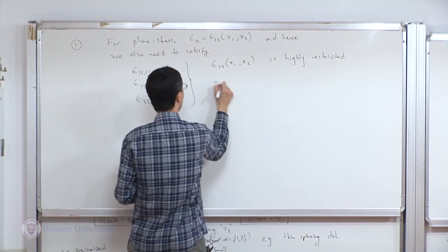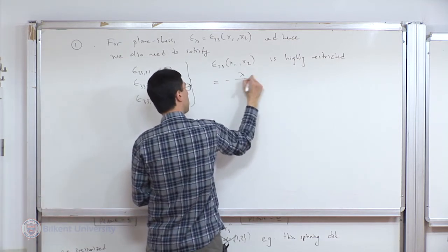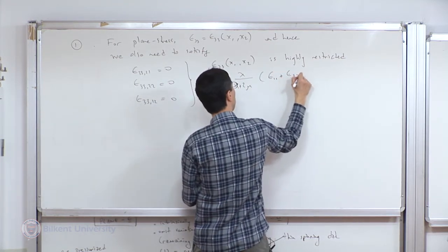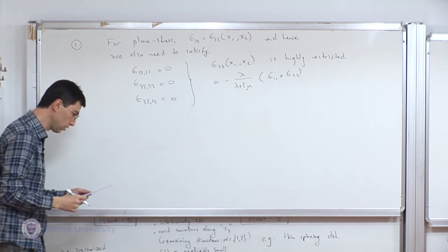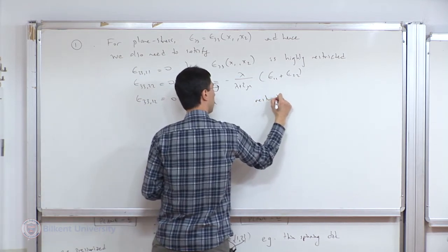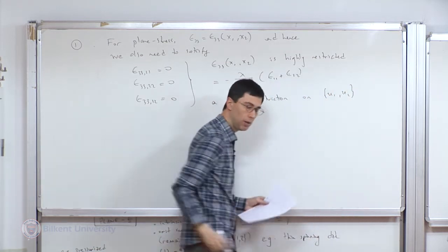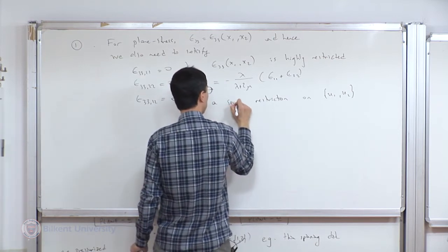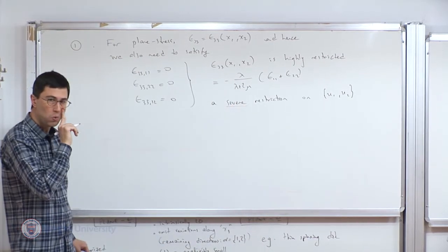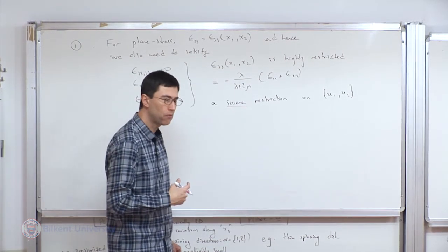And remember, these are restrictions on epsilon 3,3. And remember that epsilon 3,3 is eventually equal to epsilon 1,1 plus 2,2 multiplied by that material constant, which therefore is a restriction on the displacement components, U1 and U2. Now, it turns out that this restriction can be so severe that if we try to impose it from the outset, it's almost as though I'm going for an exact solution.